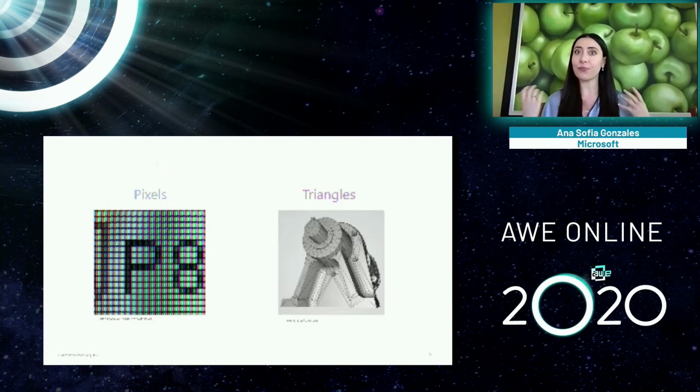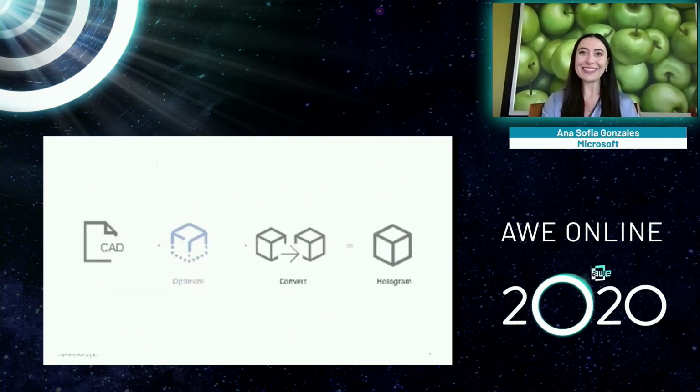So this has to be taken into account because the more triangles, the more resolution, which looks better. Imagine you have a sphere: you have to have a lot of triangles to make a very thin surface in the circle. But if you have fewer triangles, the circle will be clunky. It won't have that smooth surface, right? So that's why, let's think about triangles. Now that you really understand how 3D models are composed, let's go to the next one, optimization.